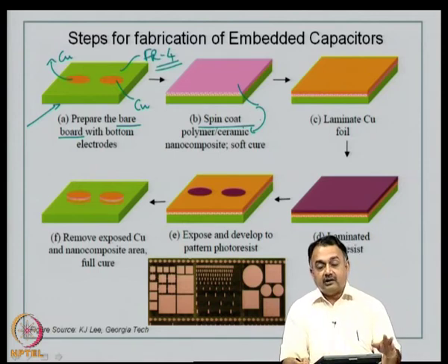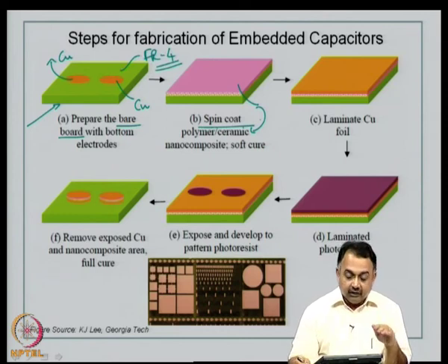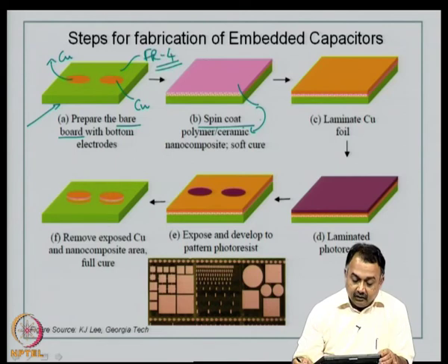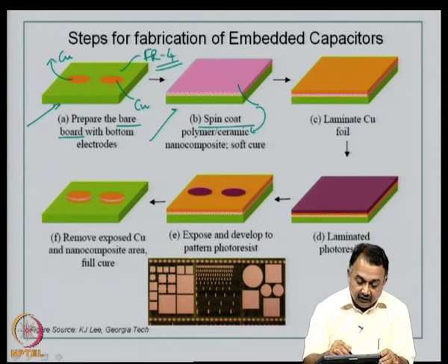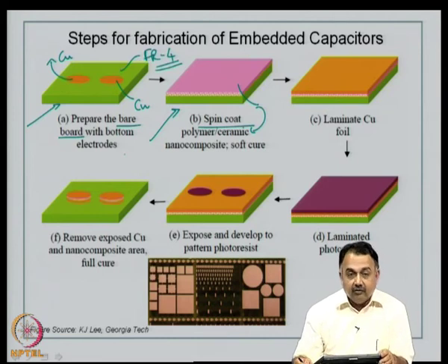The key here is the right choice in terms of volume of the media, the binding media, and then the ceramic powders. So, there should be good flow, it should be easily used in methods like spin coating, and I want to emphasize here that spin coating for areas like 12 inches by 12 inches seems very ideal, and you can get a very uniform thickness.